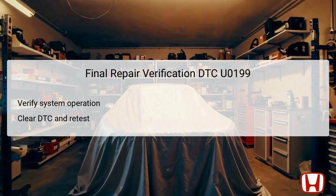After clearing the DTC, perform a retest by cycling the vehicle system to check if the DTC reappears. If everything operates normally and the DTC does not reappear, the repair has been successfully verified.